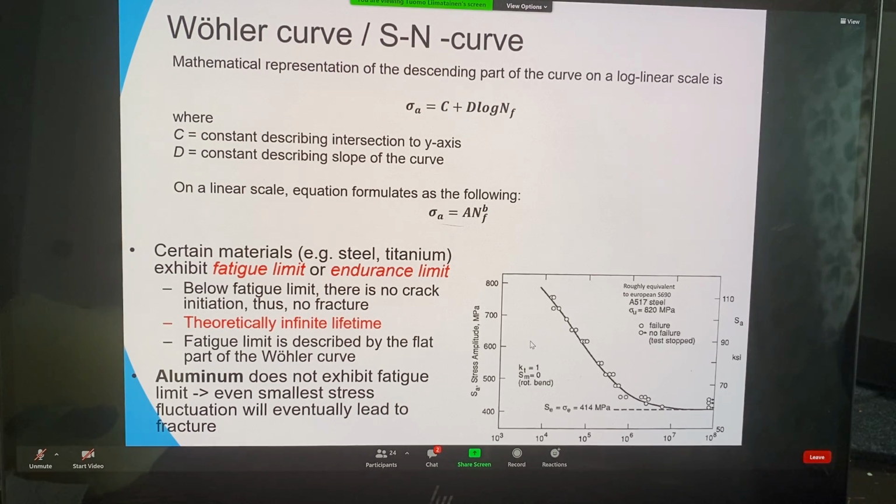This was the thing that I was wondering, that yes, those singular high loads will have an effect on the material, so that it doesn't take the lower load. Yeah, and even though this couple of high stress loads are included in the Palmgren-Miner rule, it doesn't fully take the severity into account, because really the high stress amplitudes, if they get the cracks to initiate, then a smaller amount of stress will make the crack grow.